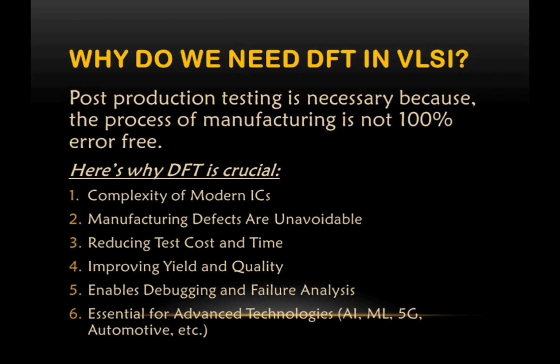is needed in VLSI. The first reason is the complexity of modern ICs. In today's chips, which contain billions of transistors, manual testing is impossible. Manufacturing defects are also unavoidable, as IC fabrication involves extremely small feature sizes at nanometer scale. Some of the common defects include stuck-at faults, bridging faults, open circuits, and timing faults.